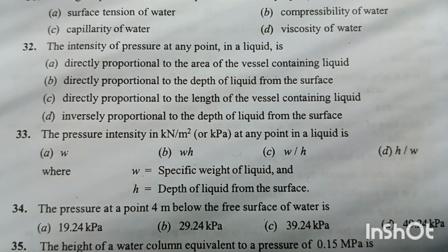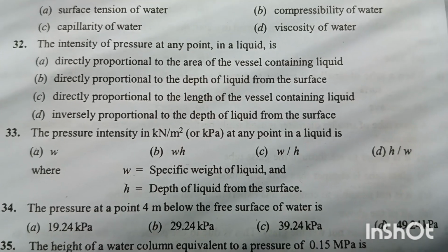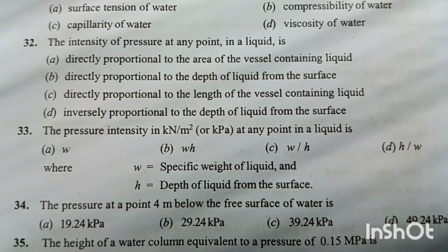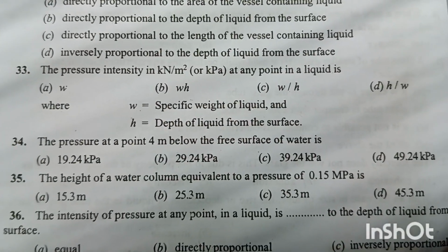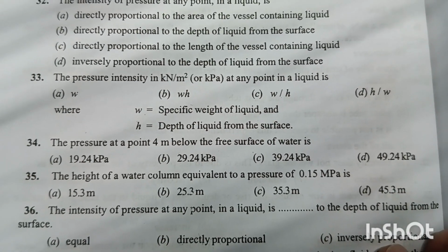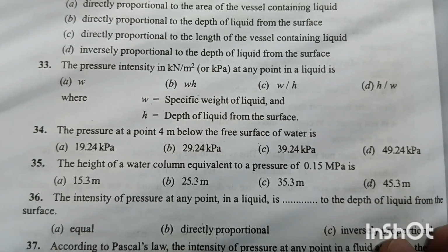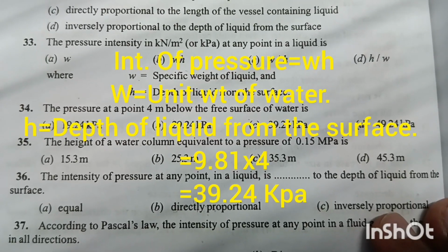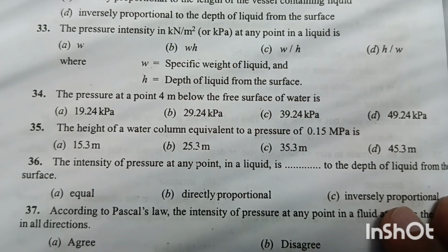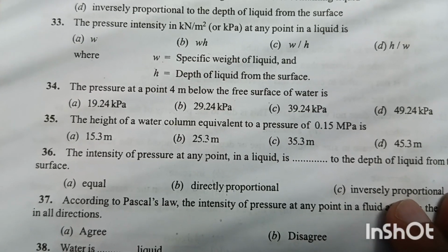Question number 33. The pressure intensity in kilonewton per meter square or kPa at any point in a liquid is w into h. Option B is right answer. w is the specific weight of the liquid and h is the depth of the liquid from the surface. Question number 34. The pressure at a point 4 meter below the free surface of water is, so intensity of pressure P will be equal to w into h. w is the specific weight of the water, which is equal to 9.81 kilonewton per meter cube, and h is the depth of the liquid given here, 4 meter below the surface of water.